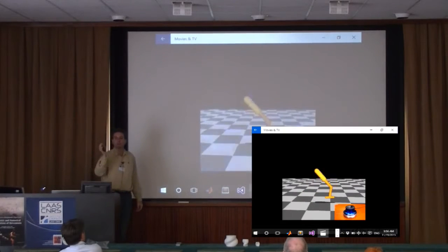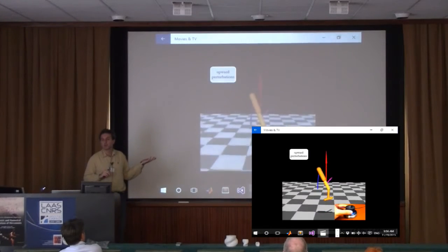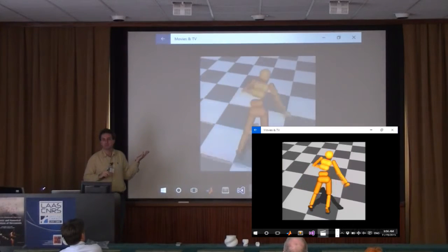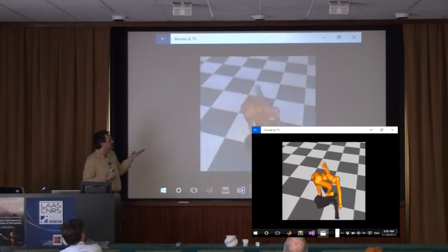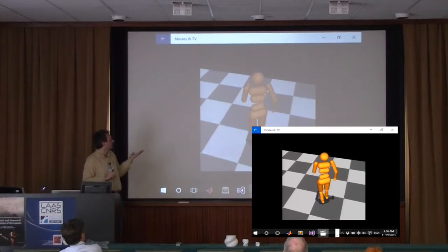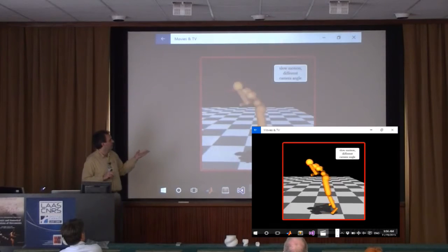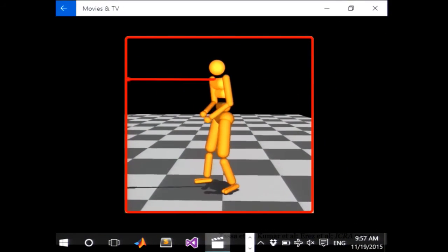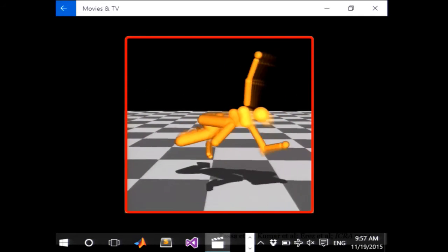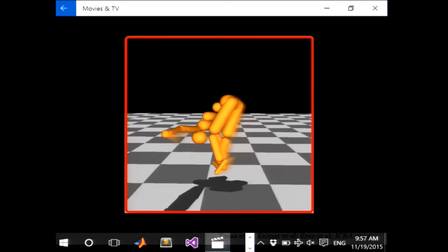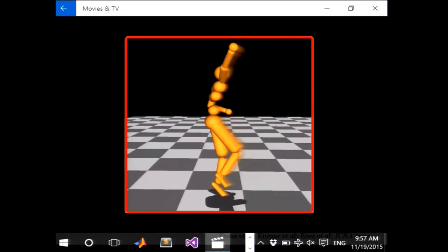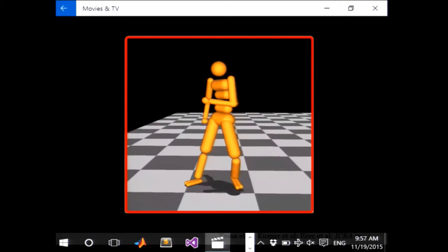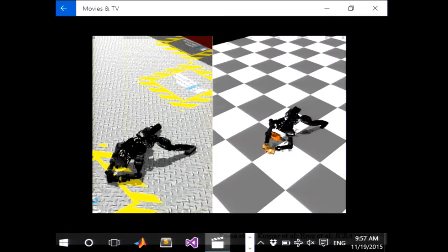So going back to a question someone asked, are these things planned or not? Well, you see how the notion of planning is a concept that we have in our heads, but maybe not that relevant to the real world. So these are planned, yes, but they're planned only half a second in the future. And then the motion that actually emerges is the result of interaction between your ongoing planning and replanning and external perturbations that we deliver here with this red arrow, for example. Here the cost function says keep your body over the feet and don't move too much. So basically stand still. And this thing invents crazy acrobatic maneuvers to save itself and stand still.